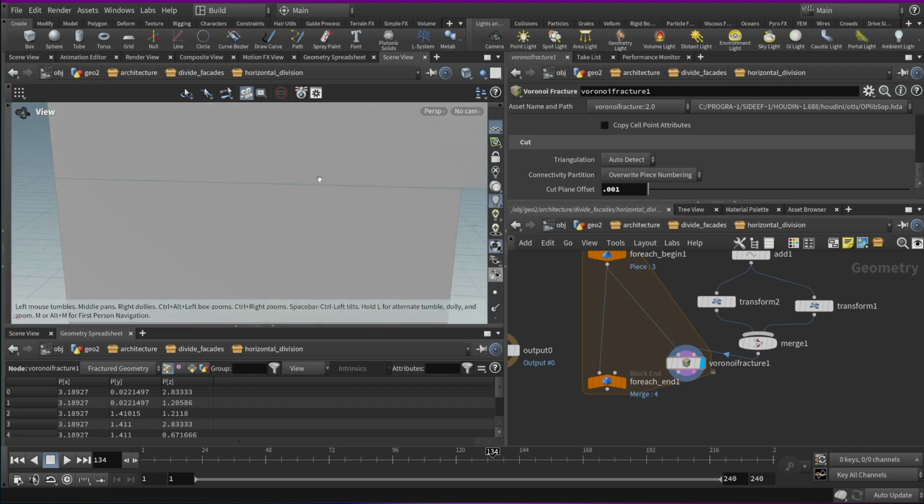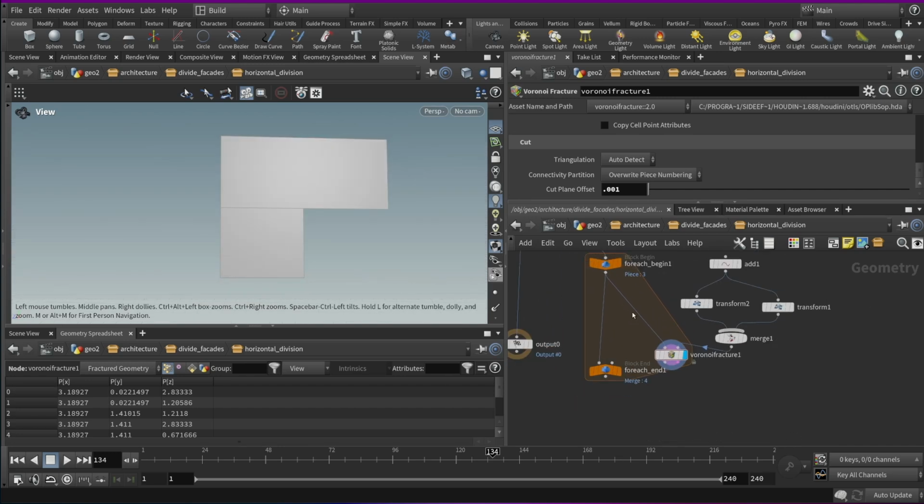Even though you get a little bit of space over there, there are ways to remedy that in a healthy way. What we have done is really just not bothered with all the difficult mess that we get when we have a cutting plane going exactly through a line, which can give very unhealthy geometry, and trying to recognize that is basically not worth it. Your original cut needs to be clean. That's one big takeaway of mine, in my experience at least. So, this is the way that we want to add this cutting plane.